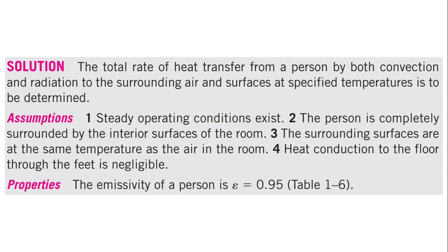that is, at 20 degrees centigrade. The fourth assumption is that the heat conduction to the floor through the feet is negligible, because a very small area of that person is in contact with the floor. Because of the very limited area in contact with the floor, we can neglect the heat conduction from the person to the floor.